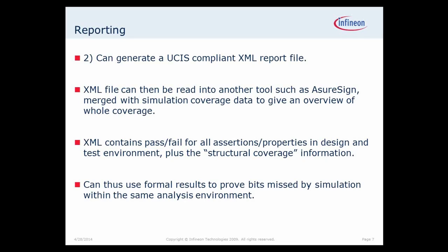So if I've then got a verification plan for my entire design, I can then map it to the coverage, and it's agnostic at that point which tool it came from. I can either say, here's a property which passes it, here's some structural coverage over here from the formal tool, it passes it, I've got structural coverage from the simulation tool for proving the other parts, and in that way you can bring it all into a coherent whole.